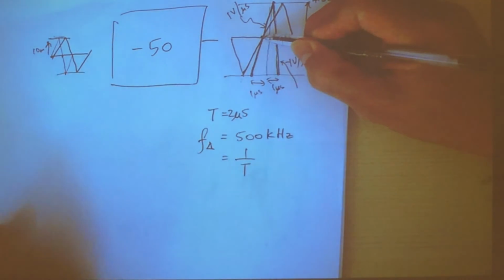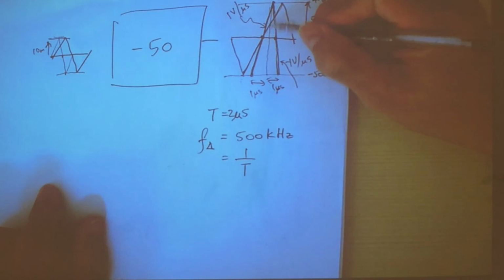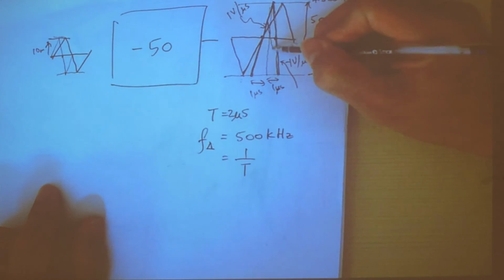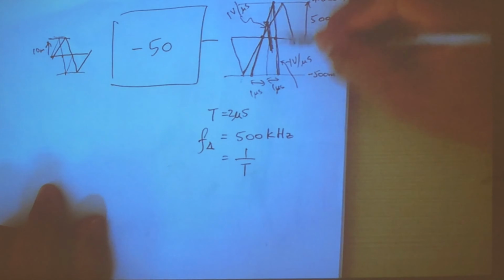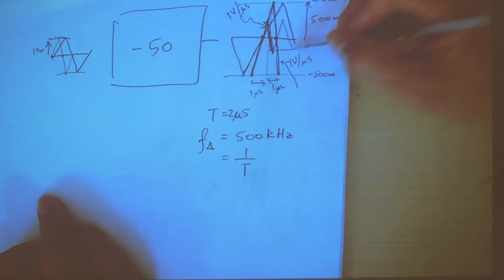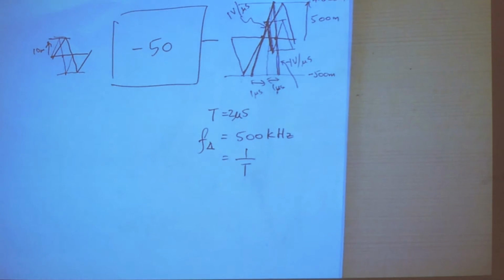Suppose this point is fixed. Then what would happen is, as the frequency increases, the slope remains the same. You end up with a peak point that is much lower. I have another slope that is parallel to this, right? And therefore you see that the amplitude has decreased, but the slope remains the same because it's slew rate limited, right? Therefore, as I increase the frequency, the amplitude starts to decrease beyond this frequency 500K. Alright? And therefore, that is slew rate limited.